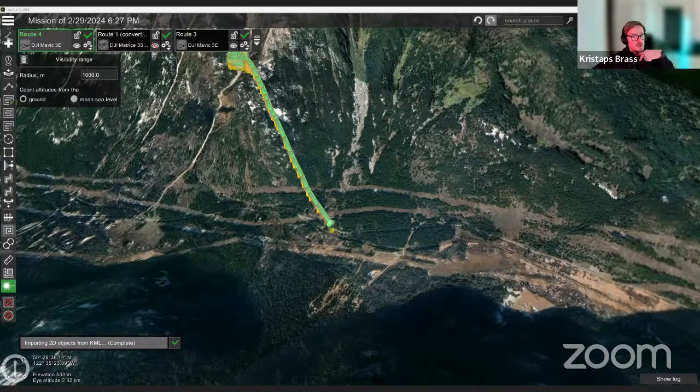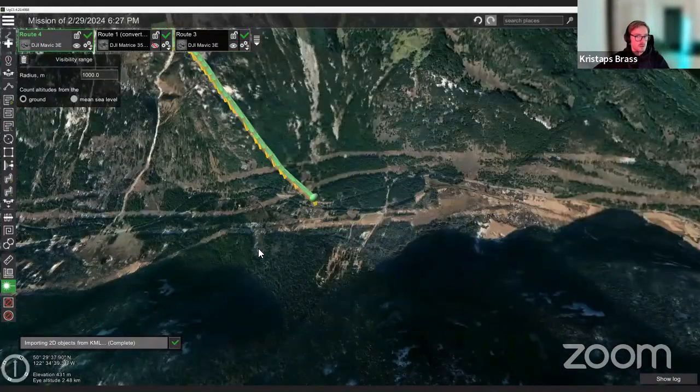Another question is from Alessandra. If you have a DJI Mavic 3 Enterprise, what's the connecting app to use? With M3 Enterprise, you need to use DJI Pilot 2. So basically with M300, M350, Mavic 3 Enterprise, and M30, you can use the Pilot 2 app to connect directly to GCS, which means you will see the drone in here, and also you'll be able to see all of the routes from GCS in your Pilot 2 in the cloud routes section. And if you want, you can also, of course, save them into local storage.